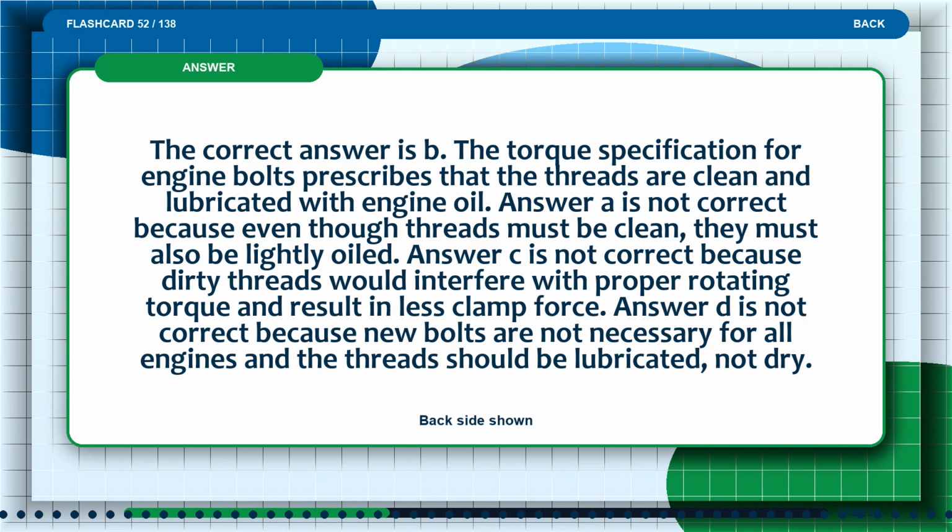The correct answer is B. The torque specification for engine bolts prescribes that the threads are clean and lubricated with engine oil. Answer A is not correct because even though threads must be clean, they must also be lightly oiled. Answer C is not correct because dirty threads would interfere with proper rotating torque and result in less clamp force. Answer D is not correct because new bolts are not necessary for all engines and the threads should be lubricated, not dry.